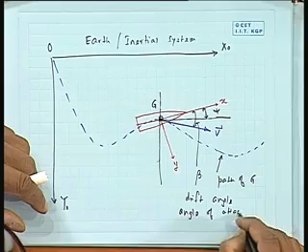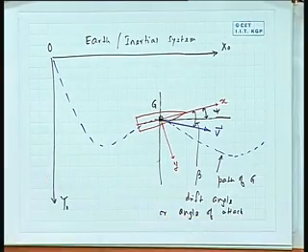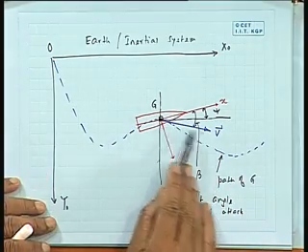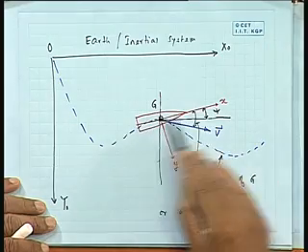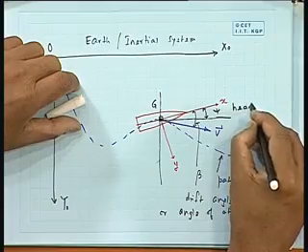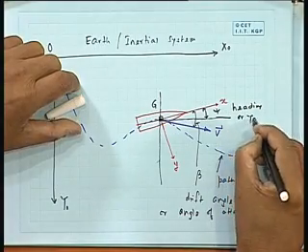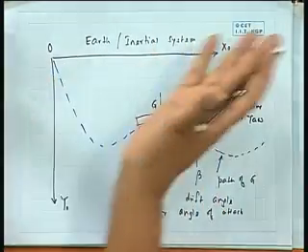So, you see, what the velocity vector makes with the x axis is what is called drift angle or angle of attack, because that tells me which direction the flow is coming from. In fact, the fluid force depends only on that, whereas heading angle just tells me which direction it is heading. You can say this is heading or yaw, heading is same as yaw, right. And I have got of course this x y system here.